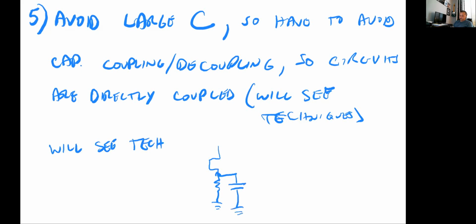That was to establish this as a signal ground for the signal, but we still wanted that node to have a DC bias to give us the gain control for the transistor.